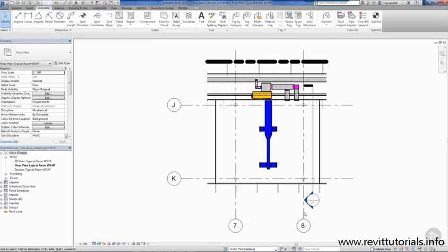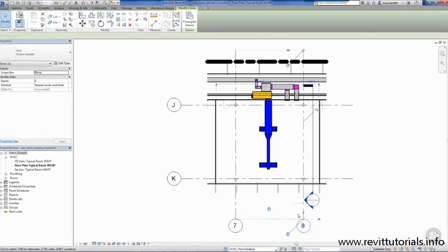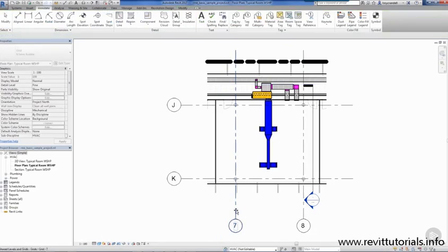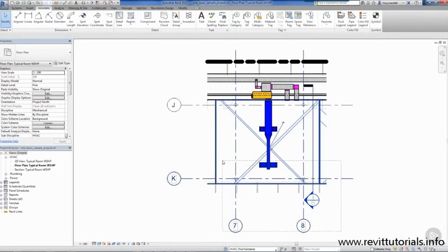It's the click and drag filter. We have this one off in our firm because it's easy to select things in the background in certain views and accidentally move them. Now, turning it off requires you to select the element first, then move it.